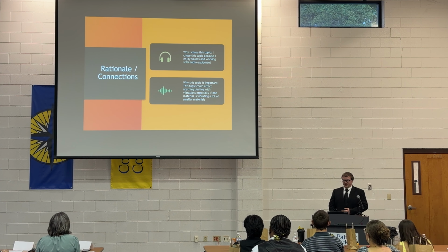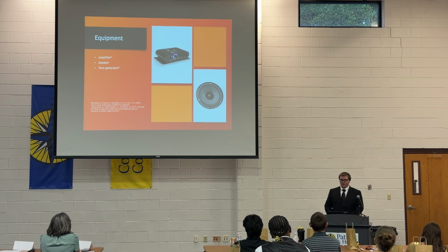And I needed a speaker to actually cause the vibrations. So the way a speaker works is it has a magnet and a coil and a cone. The cone is the larger part of the speaker. It's usually made out of paper, and it's attached to the coil. And when you send power to the coil, it becomes an electromagnet that is attracted to the magnet below it, and this causes a vibration. And doing this several times over a second will produce a sound wave.